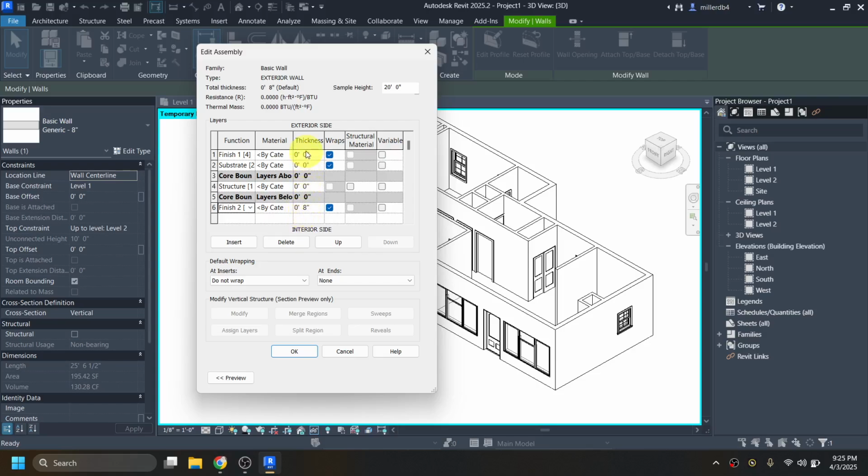Next, I'm going to adjust their thicknesses so that they all have true material thickness. I'm going to use the same materials and measurements that we used from the 3-room shed. So our siding is going to have a total thickness of 3/4 of an inch.